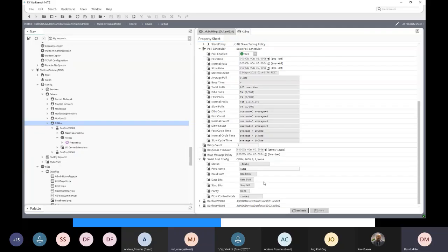You know, if you can connect to just one device with a single cable from your FX80 to one N2 device with nothing else connected, then if you can get that to work, then you can work at getting everything to work. So best case is you unplug it out of the NAE, you plug it into the FX80, and it all comes online and works. That should be what happens.